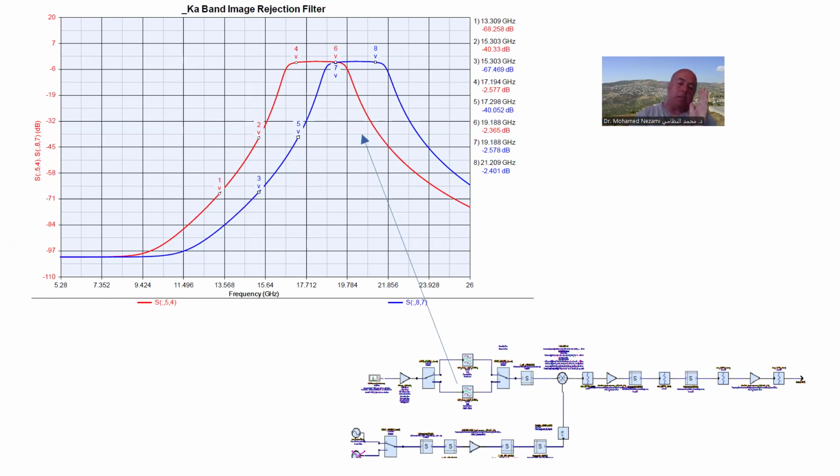Now, here's the catch. If you look at SATCOM equipment, in some cases they use, like I use here, a switch between bands, or you could actually use a two-way splitter in here. You can use a two-way splitter and a two-way splitter in here, and that way you don't have any switching mechanisms, which will become critical and may have some issues. But I chose to do it this way. So we've got the two bands.